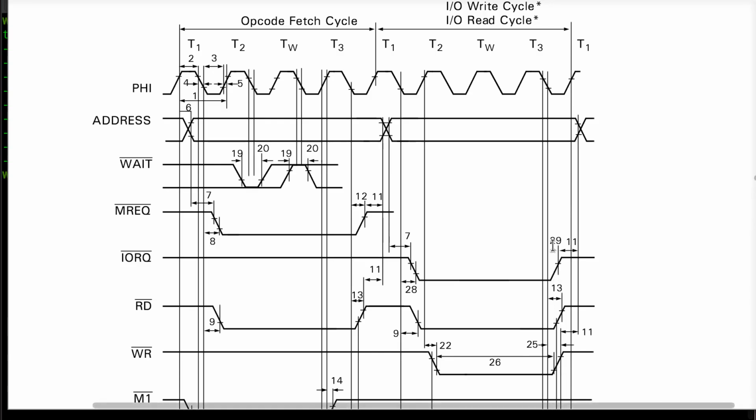However, if you use this rising edge, you don't know whether it happens almost immediately after T3 or way over here on the rising edge of T1, which gives you a fair amount of variation inside the circuitry of your FPGA. What you really want to do is bring it in at a very known point in time on a very specific edge of the main clock that synchronizes everything going on inside the FPGA, which is the fundamental basis of all synchronous design.